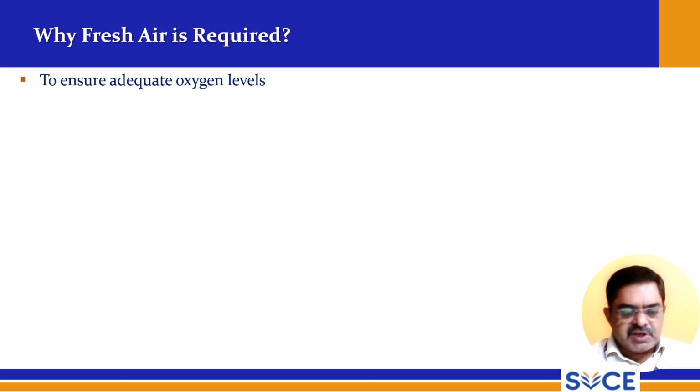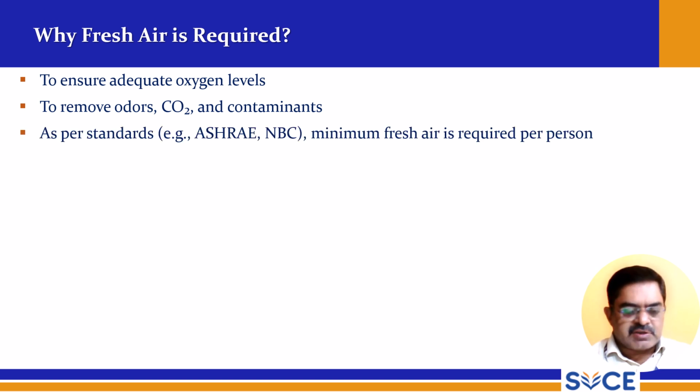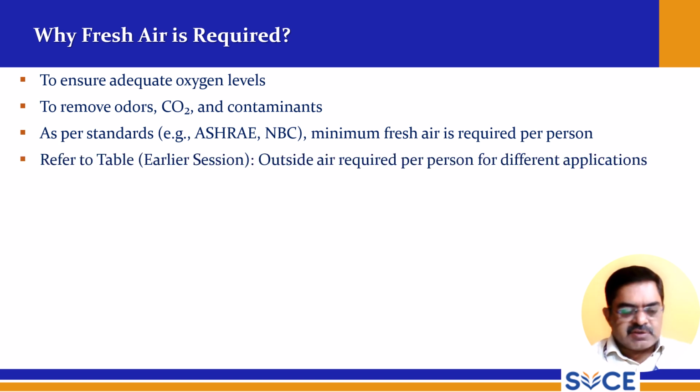So why is this fresh air required? To ensure adequate oxygen levels, to remove odors, CO2 and contaminants. As per standards ASHRAE and NBC, minimum fresh air is required per person, and that is the table: outside air required per person for different applications.